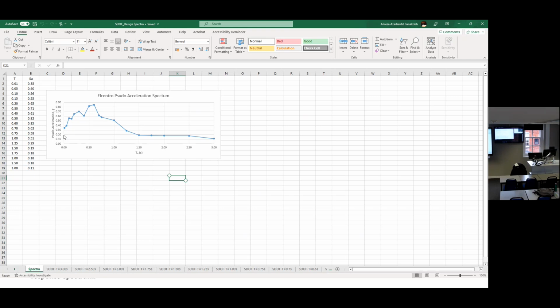What you should really do in practice, if it's not okay and you are stuck with that kind of steel, is go for a third trial and really make your section bigger. Because with that section, you're really at the topmost you can be.